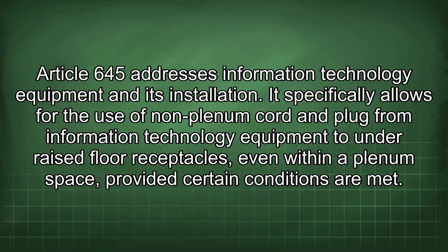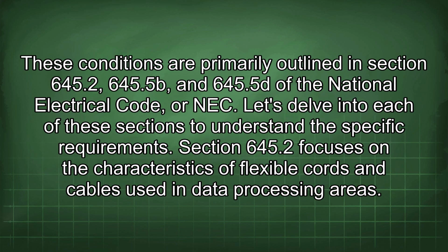Article 645 addresses information technology equipment and its installation. It specifically allows for the use of non-plenum cord and plug from information technology equipment to under raised floor receptacles, even within a plenum space, provided certain conditions are met. These conditions are primarily outlined in sections 645.2,